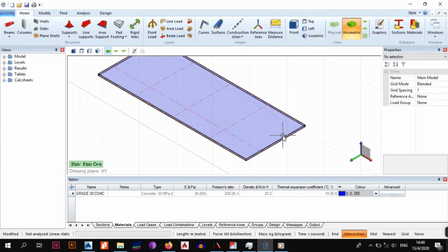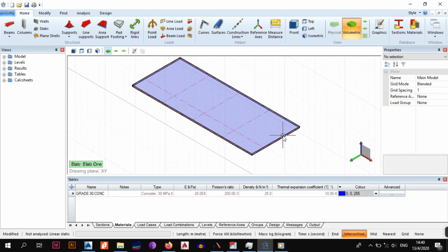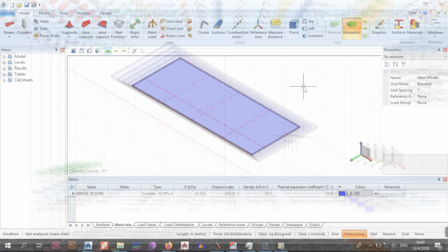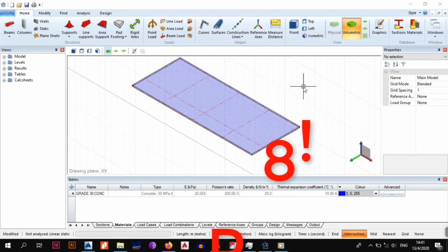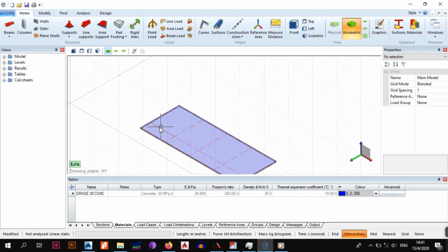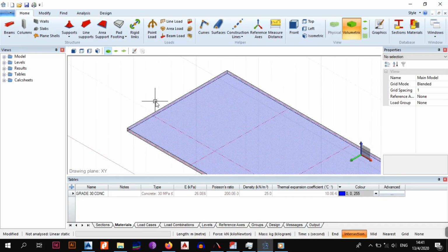And now the next thing we need to do is add the beams. So that is the next step that we're going to do. So let's get to the next scene. Okay, so the next step that we want to do is add the beams. This is easy. I think you now know what we have to do, and we already know where our beams are. So we're just going to click on beams. What type of beam do we want to add? In our case, we have monolithic beams, and they're different from just the beams. And also, I'll show you an advantage of adding monolithic beams.